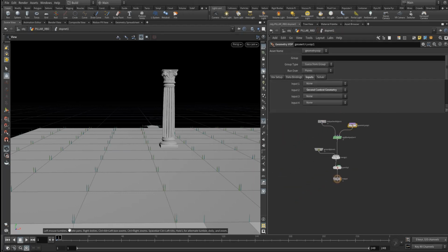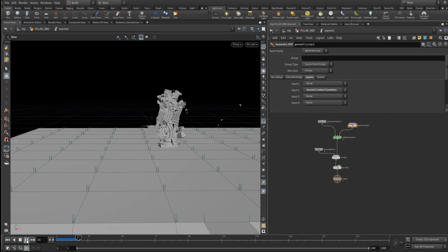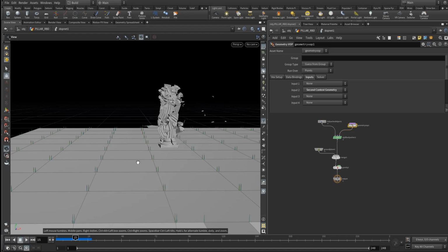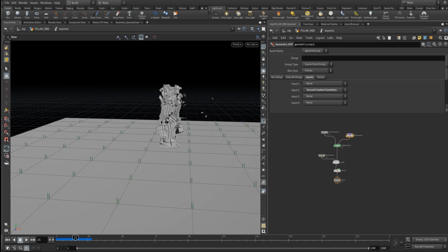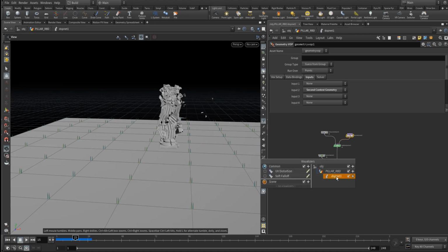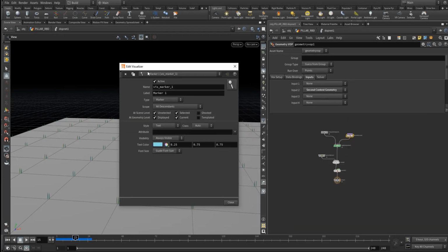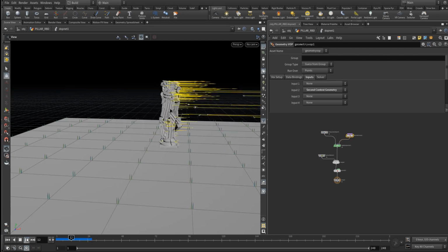So now how can I check whether my force is working or not properly? It's working, but in a very minimal way, I think. Yeah, so go to this Google map type icon over here. On this you can see the plus button. Click on this marker, and you can name it force, label as force, and this attribute, I want to visualize my force attribute, so type force over here, text style to vector, and show arrow tip. Is it working on? Yes, it's working.